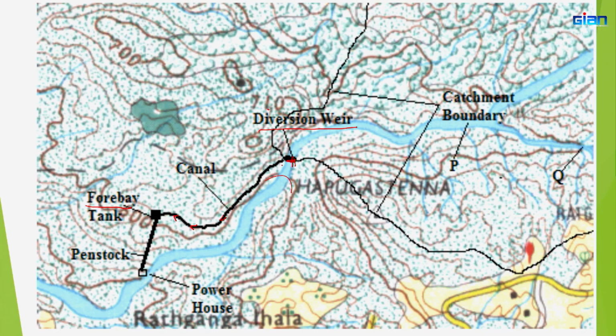I told in the previous discussion that normally the canal has a very low slope. Normally about 1 to 1000 as I said earlier, but the exact amount you can calculate using a different formula, but roughly about 1 to 1000. That means you go almost parallel to a contour line, right, because contour lines are lines of equal height. You need only 1 to 1000, that is 1 meter drop for every 1 kilometer. Therefore, you will plan your canal very parallel to contour lines.